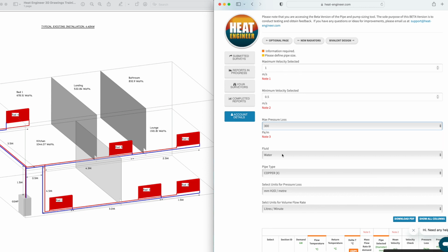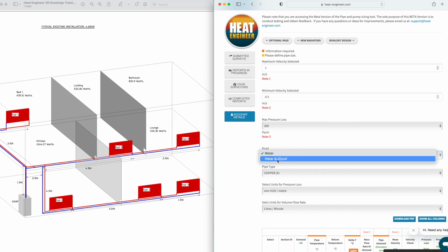We've also got your difference in fluids. So we've got water, and we've got water and glycol. Not sure how many people are using glycol these days, for the simple reason that if anybody's done my course or the Heat Geek course or Kim's course for the Heating Academy Northampton, you'll know that the specific heat capacity of water changes quite considerably when you're adding 25% or so of glycol, and it drops it down to about 3.7 as opposed to about 4.2. So it's thicker, if you like, and so it's harder to pump around. So your pump running costs, etc., do change. So a lot of people are using antifreeze valves, or sometimes even not at all. But that's the basic. I would stick with water.